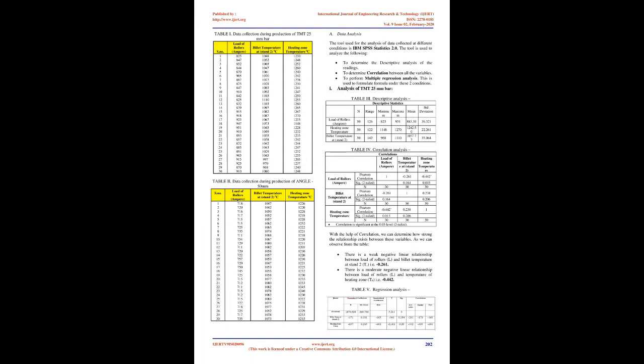B. Statement of problem. The mill was undergoing loss of production due to variations in hot rolling process parameters. The following problems were identified. Variability in quality standards of finished products in the same profile. Change in operational parameters during the rolling process of the mill. Increasing cobbles in rolling stands, which gives unfinished product. Roll breakage due to uneven rate of rolling and lack of maintenance. Generation of excess load in the rolling stand during operation. High-speed rolling gives different types of breakdowns. Uneven temperature of heated billets supplied from the furnace.